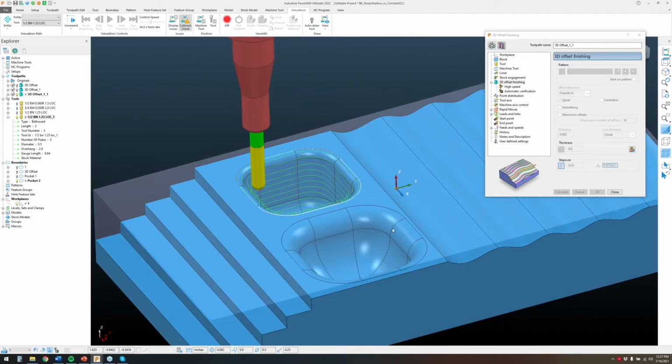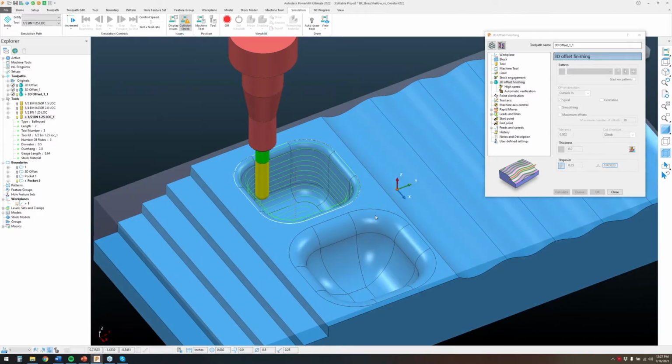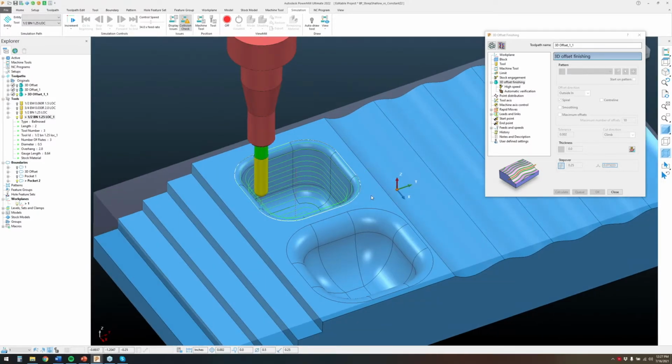So you can see that the 3D offset also does a pocket just fine that has maybe an upper corner fillet, lower fillet, as well as straight walls. So this toolpath itself is actually very versatile as for 3D finishing. So just always know that in PowerMill, a lot of ways to do one thing. So that's kind of what I wanted to show you about just this toolpath. So the 3D offset finishing, it's mainly good for those near horizontal surfaces, but you can tackle more of a square pocket with fillets or some 3D portions inside of it.